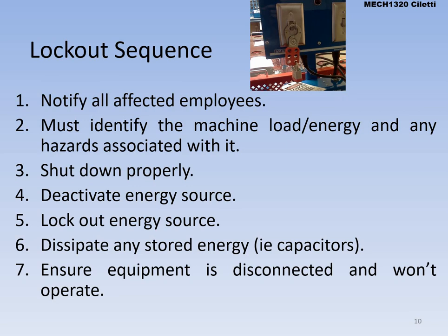So we can look at the top picture there that we had on the previous slide. Putting the hasp through it so no one can flip the switch up, and you're putting a lock on it so that no one can remove that hasp. So you've officially locked out the energy. Make sure that you dissipate any stored energy, like capacitors. Their whole job is to store energy and dissipate when called upon. So make sure that you discharge those, because if you touch those live, that could hurt.